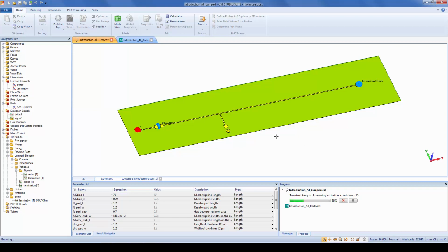And you can see that that might become time consuming. Of course, this is a very simple model, but for a complex model where the 3D simulations might be more complex or more time consuming, changing these values and rerunning everything just because I want to change the value of a resistor seems not acceptable. And this is something which we can solve much better with a coupled simulation. But let's first take a look at the results of the simulation.